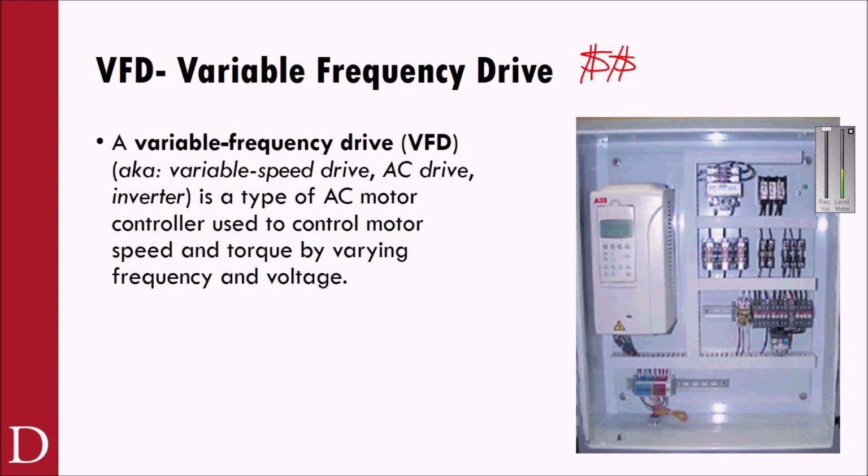If you wanted to control a motor and you're going to go buy a drum switch as an example, you might spend $250 on a drum switch. I'd venture to say for a 1 horsepower VFD, for probably $300, you can get a pretty nice 1 horsepower VFD and have a lot more control than just direction.